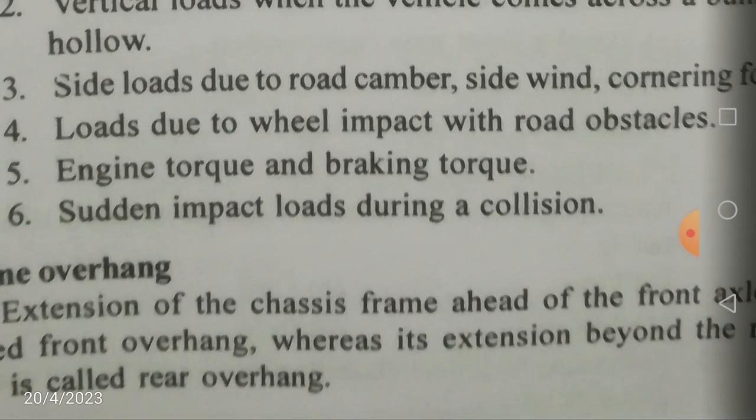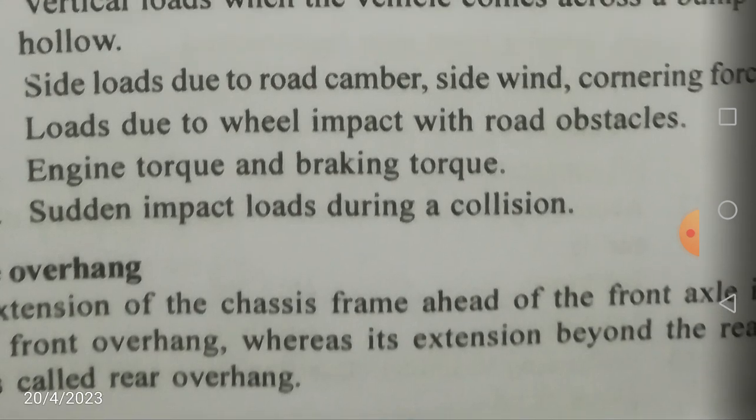So now the third one is camber. So what is camber? Camber will be viewed in the front view, whereas caster will be viewed in the side view. Camber is nothing but your wheels are bent at some angle to the vertical, to your road wheels. This particular angle is called the camber angle. The caster angle will be seen in the side view, friends. This is the angle made by your steering axis with the vertical drawn at the wheels, the central vertical axis of the wheels.